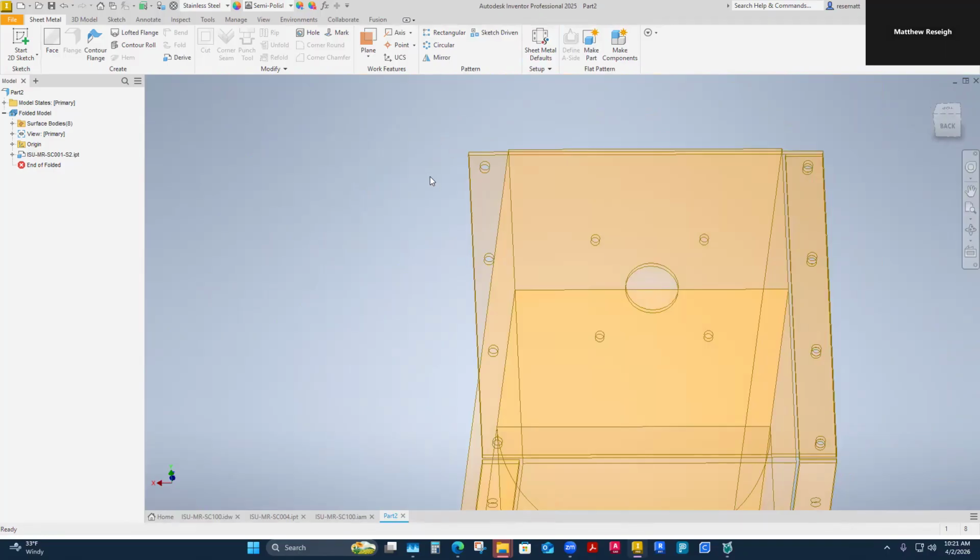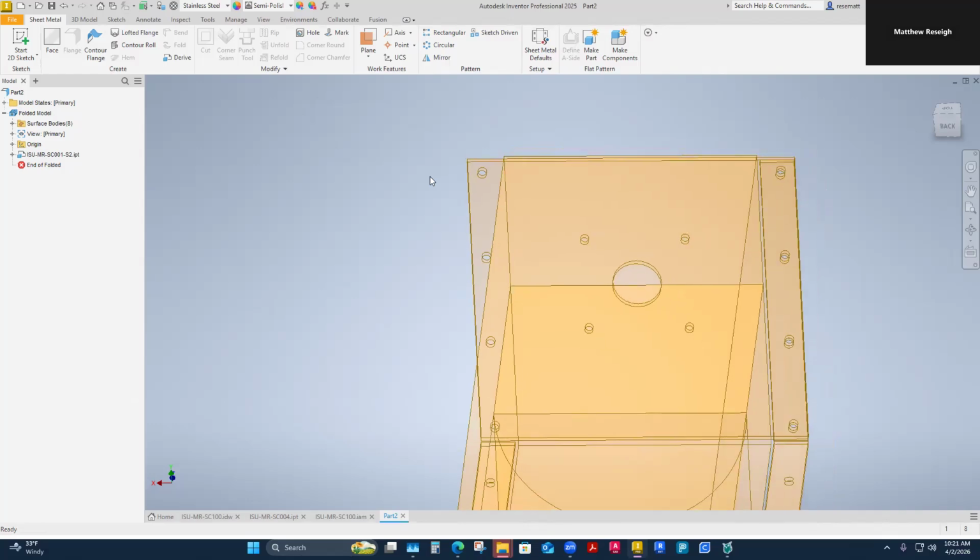I don't even have to mirror the part to actually mirror it in use. I could mirror it in Inventor and say, well, mirror that as I create it. But really, I'm just going to use that same part twice. I'm just going to assemble it flipped. This is something you'll get better at too, is realizing when you need lefts and rights, and when you realize that I don't need them to be totally different, that the left will serve the right as long as I constrain it in there on the right.